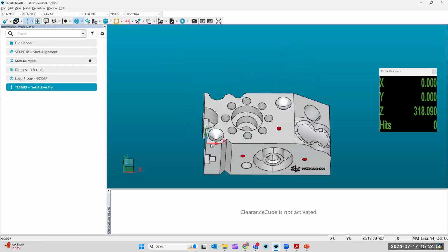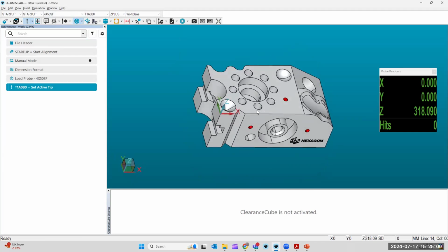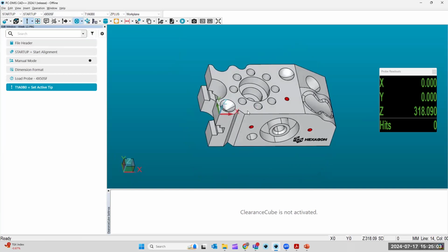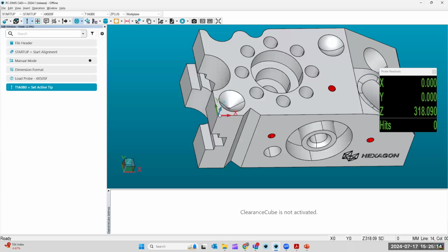Now I'm going to program an ABC alignment. ABC is the simplest form of a 2D alignment. What it does is it gets your coordinates from your machine axes, from your machine coordinates, to your part. It identifies an origin on the part. And in this example, it should match this CAD origin exactly, because Z would be constrained by A, B is going to constrain your Y, and C should constrain the X. So we know that the origin should be in this corner up here. Okay, so we're going to do a two-dimensional alignment.